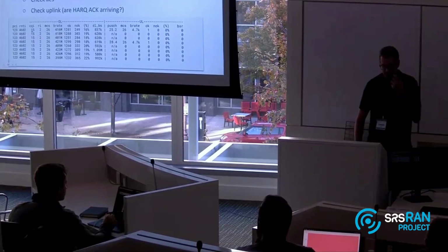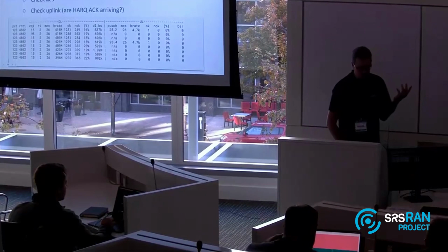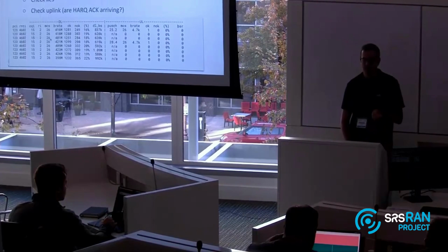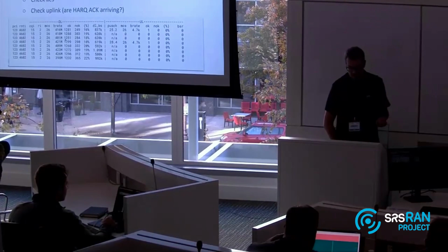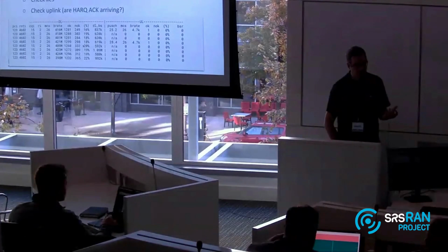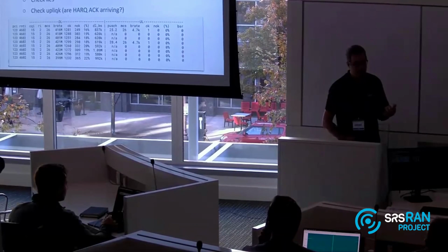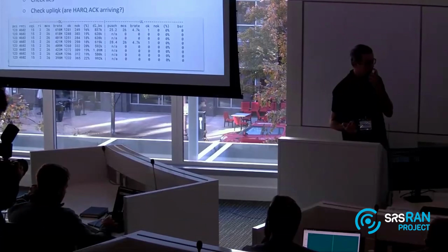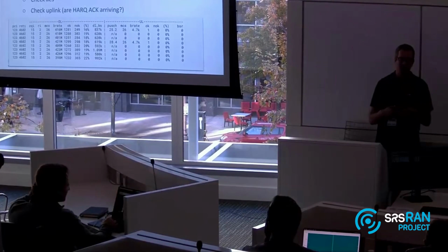Here, what this is telling me is that the UE is seeing a good channel. The UE is reporting a SINR of 15, and we are choosing an MCS that correctly corresponds to the SINR. So what happens? Why is the BLER so high? One potential problem here could be that the uplink is not correct. Remember that the UE sends the acknowledgements on the uplink.